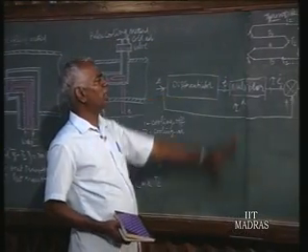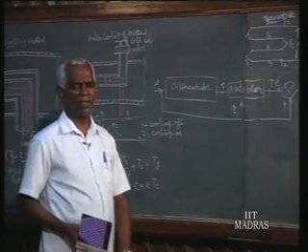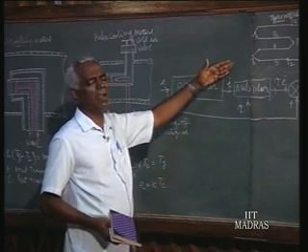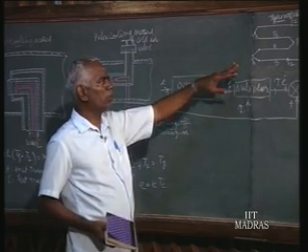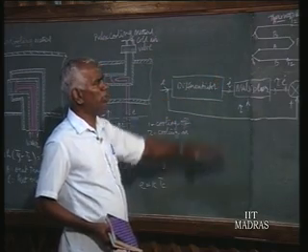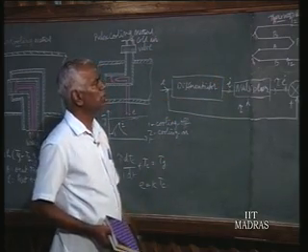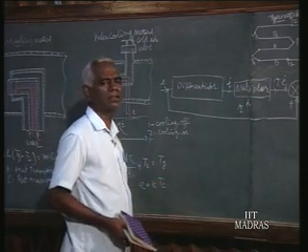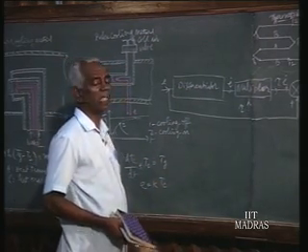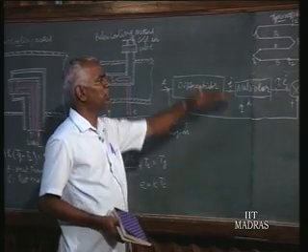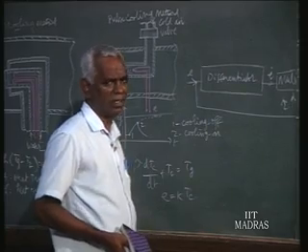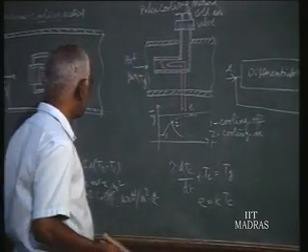Naturally, the thermocouple wire can be used only when the temperature of measurement is lower than the melting point of one of the thermocouple wires. We have two elements, and one element will have a lower melting point. So the measurement temperature should be less than that. That is the limitation. Suppose the temperature is high and one of the thermocouple wires may melt at that temperature. Then you can adopt either of the following techniques.